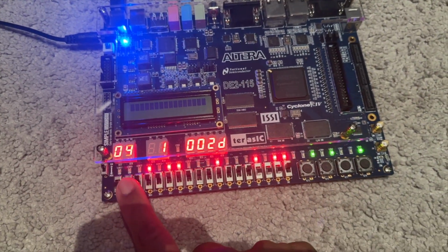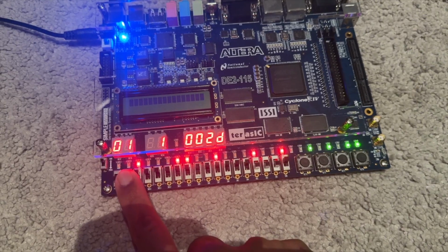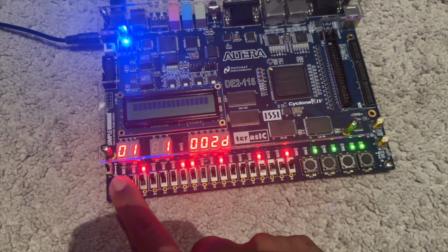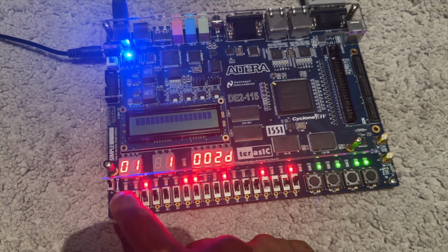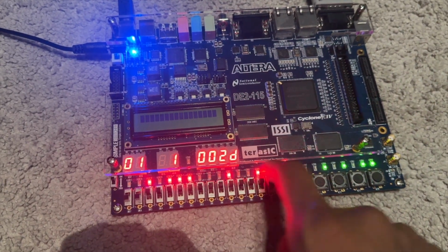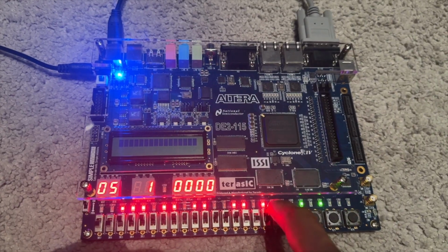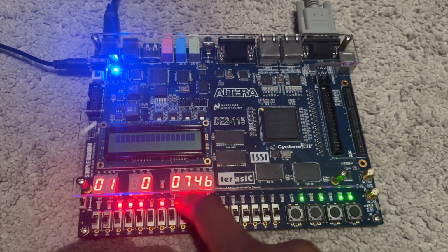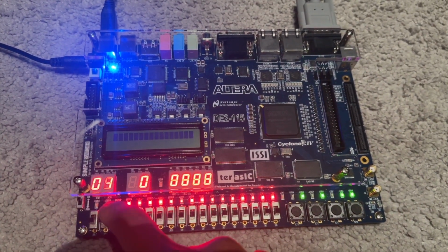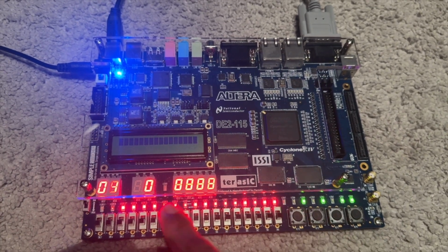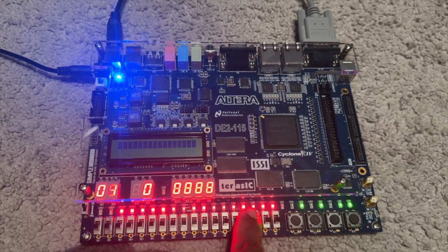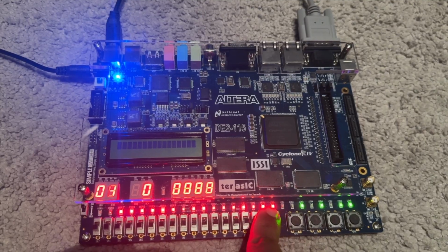This switch here will set the clock hold, and then the last switch sets memory suspend. And then of course, if you want to reset the program, you can just press this button here, which will reset it. And then we can go back to max clock speed by turning off all these switches here, in which case the lights will appear to not be blinking because it's running so fast.